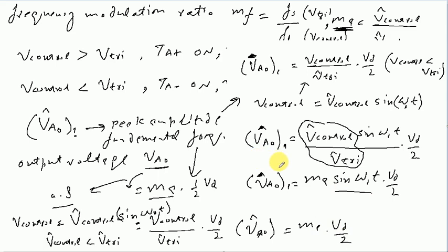For the fundamental frequency component, this term will be equal to 1, and we will be left with this particular term. The point of interest here was to determine how we can achieve an output voltage signal of the same frequency as the control signal's frequency. From this equation we can see that it will vary according to the frequency of this control signal.